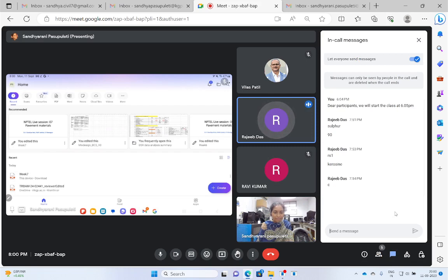I was asking about this question: addition of elastomer to bitumen improves the elasticity. So how to quantify that? To quantify that, we have the test of determining the phase angle. When you determine the phase angle, if the phase angle is 60 degrees for the binder, after adding the elastomer, that will actually reduce. So this is an indication that addition of the elastomer reduces the phase angle.